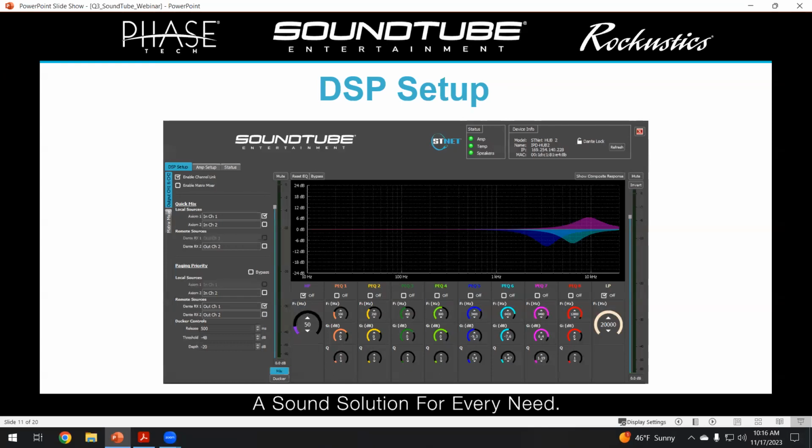So it is an 8 ohm speaker output. The lowest we really ever suggest is like a 6 ohm load, but anything below that, you kind of risk overcurrenting the switch. Yeah, let me, Mike, let me jump in and also answer that question.